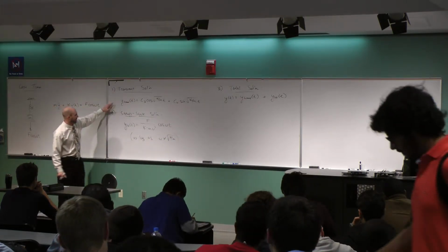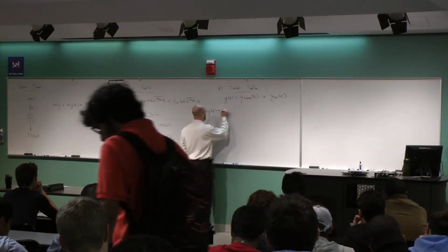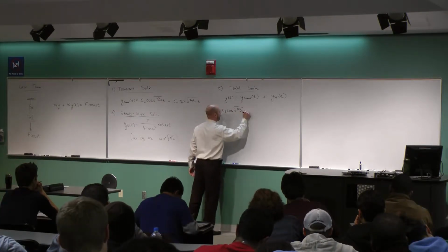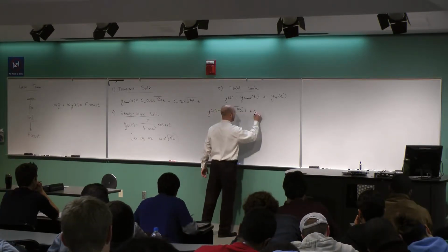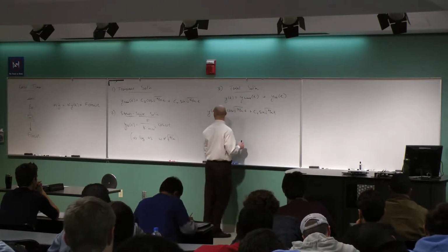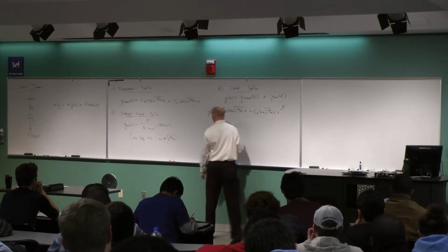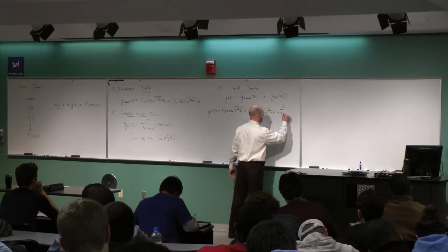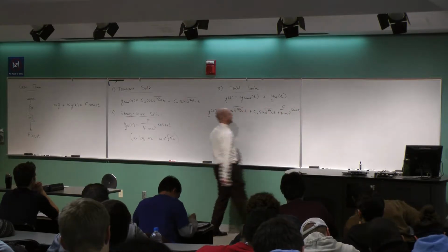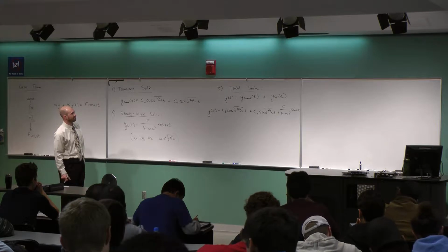At this point, I've got the following. y of t, the transient part, is c3 times the cosine root k over m times t, plus c4 times the sine root k over m t, plus the steady state, which is F divided by k minus m omega squared, times the sine omega t. I've got all of that as the solution at this point.